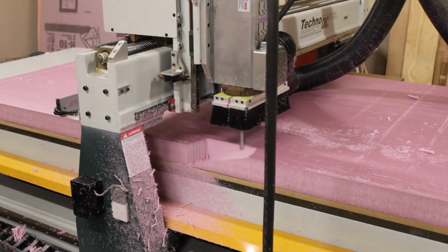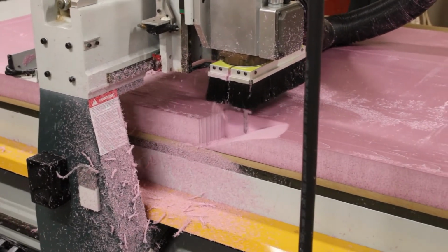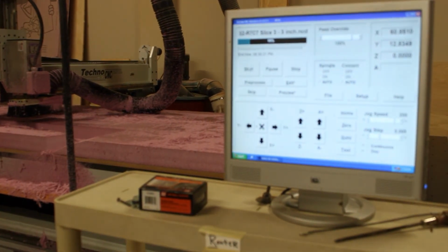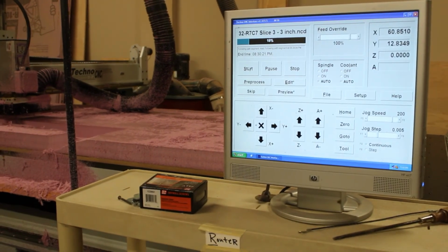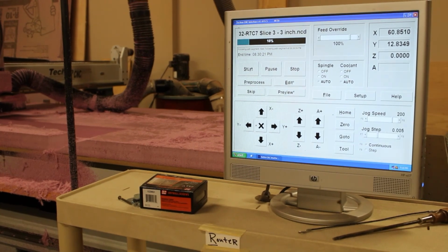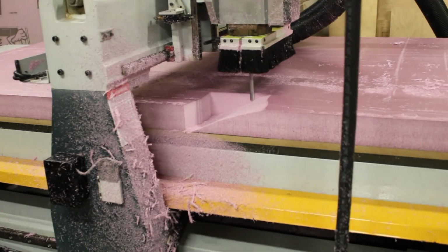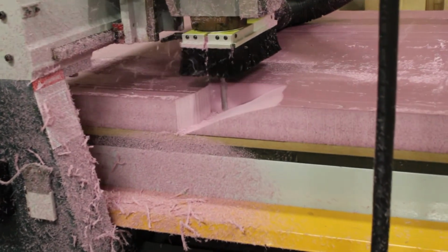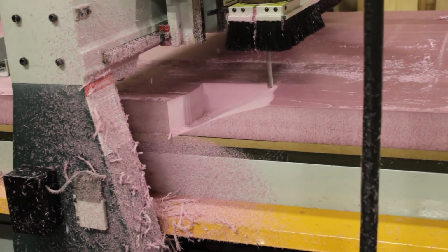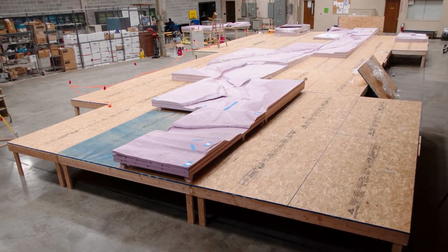This building insulation foam that we chose here was a little bit denser than is commonly sold at your local hardware store. However, it was still readily available, and the denseness of that foam served a couple of purposes. One is that it was able to stand up to the routing without fraying and coming apart in that process. But also the tightness of that foam would help us later on with our water tightness. Once the panels were routed, these were 4x8 panels that ranged anywhere from 2 to 4 inches thick.